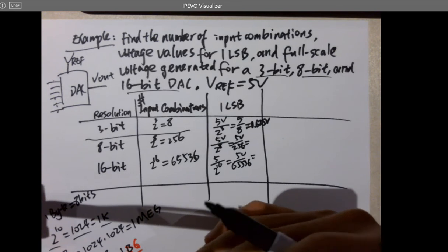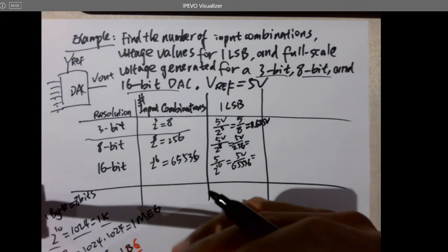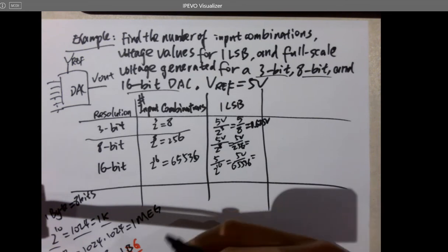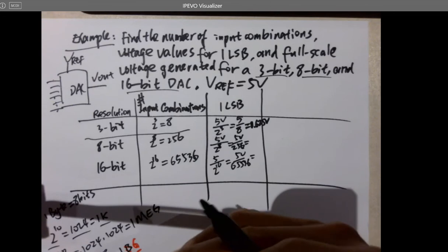The highest resolution I have ever seen in my life as an ADC is called HX711, and that's the ADC for strain gauges. You can directly buy the module for like $1 each. It's pretty easy, and it's a 24-bit resolution ADC.